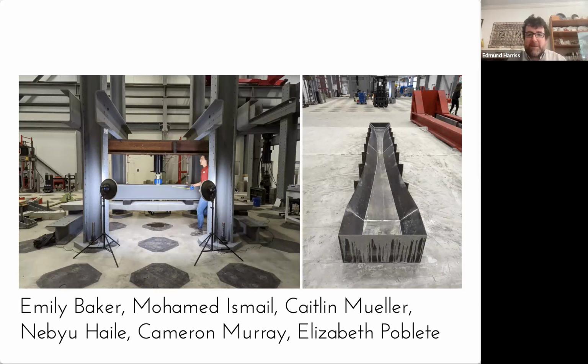And these metal beams that you look at in the frame, they're doing that same thing. They are basically creating this eye shape, which is going to give you a lot of strength with a lot less metal than a full box. So by changing the shape, you can get a more efficient use of materials without actually affecting your strength.